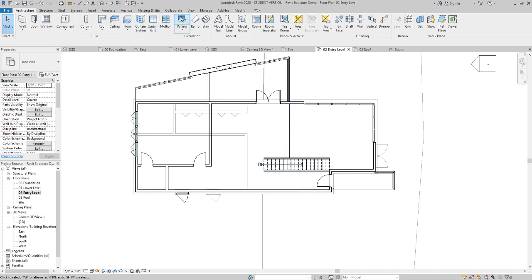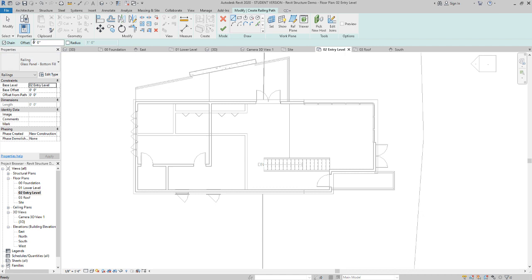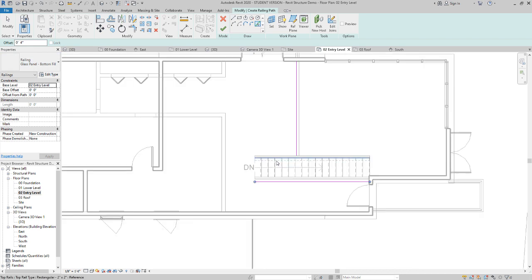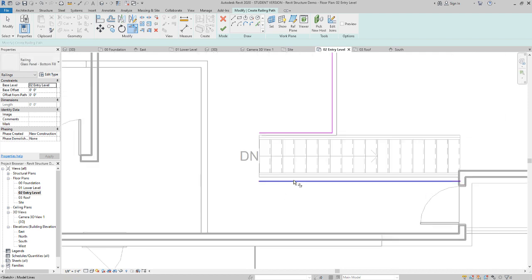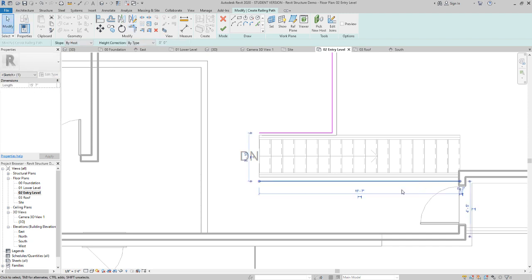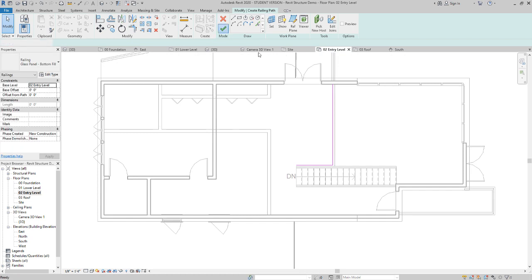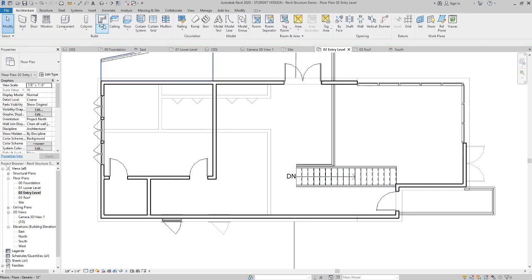So we're going to do the same thing. We put a railing, do that offset of 4 inches, and pick lines. Pick this guy towards the inside, pick this one over here, and pick this one over here, and then we do a corner tool of here to here. And oh, it's not going to let us do this, right? Because it has to be connected. So we can hit escape twice, delete this one, say check, and then we can add one more railing.